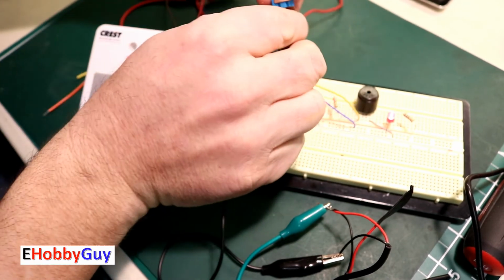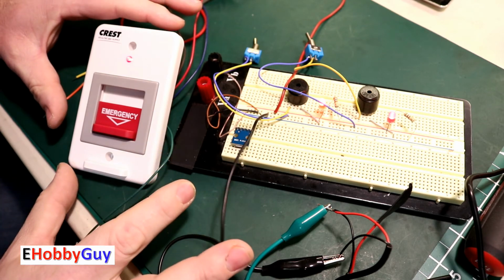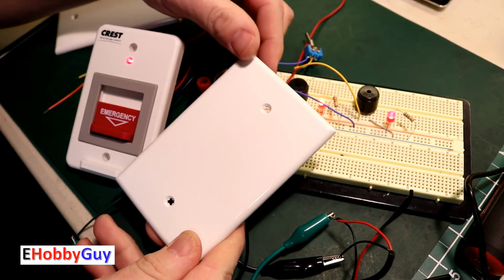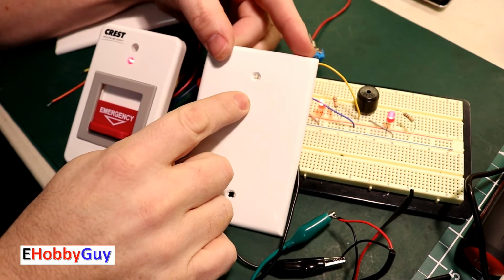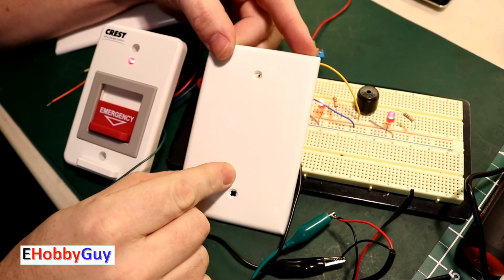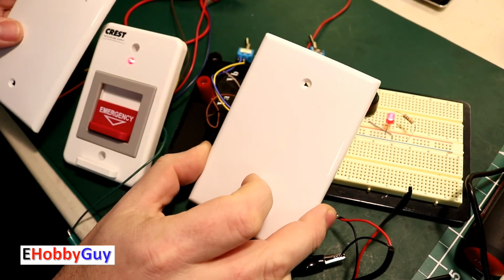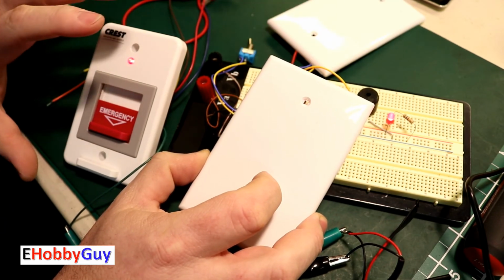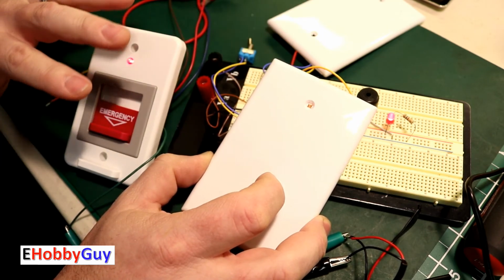Silence. Silence number 2. Now let's see if we can put this into a real practical, real world use. Here I have two blank single gang wall plates. I could easily mount an LED here, a buzzer, and a bypass switch for each set so that we could interconnect and mount these in a wall in locations other than where the person in distress might be. And then we can interconnect the three with wires and the power supply.